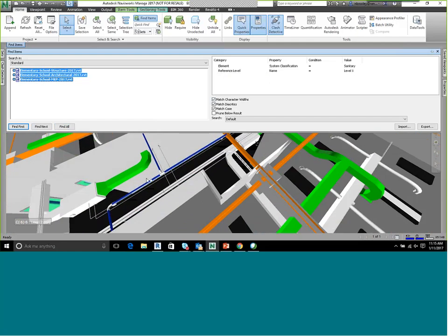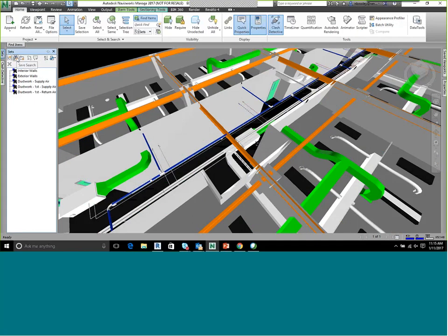And so I like the rule. So it already selected the items. And now what I'm going to do is go to the Sets palette. And I'm going to hit the binoculars, Save Search Set. Excuse me. I'm going to type in level 1, or maybe I'll type in piping first sanitary.